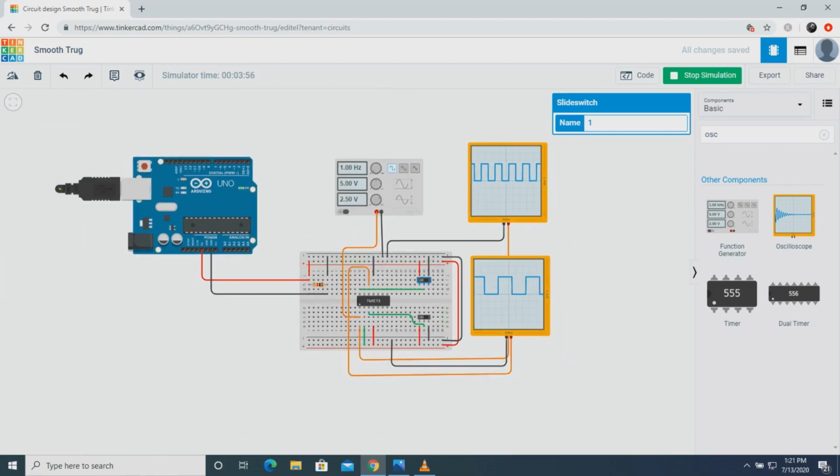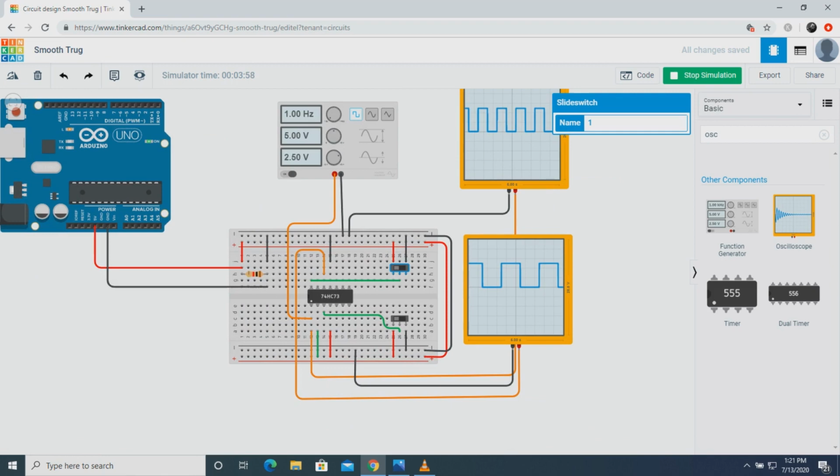The way I have shown you is one way of powering your IC, but you can also use the power supply here. The power supply is very difficult to adjust, since you have to set the voltage and current by moving the knobs, so it's better to use this way. But if you are comfortable using the power supply, you can use it. It's not a matter.